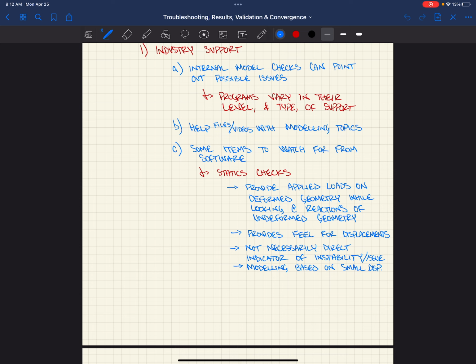And yes, it does, it'll poke up an error over there saying that you might have a statics imbalance, right? But it's very helpful if you were looking at service level live loads on your structure, you can then say, all right, my reactions are 67.653 in the vertical sense, right? Based on my hand calculations, I should be really close to that, right?